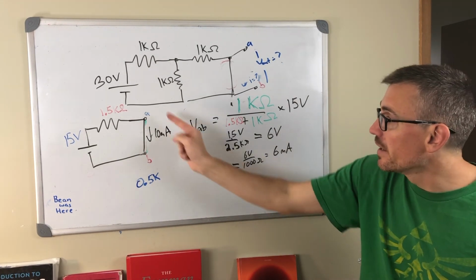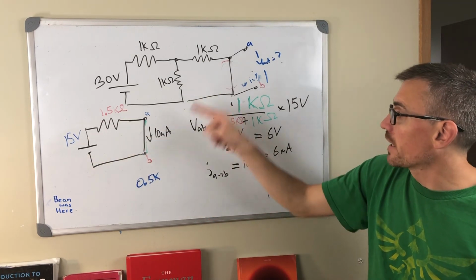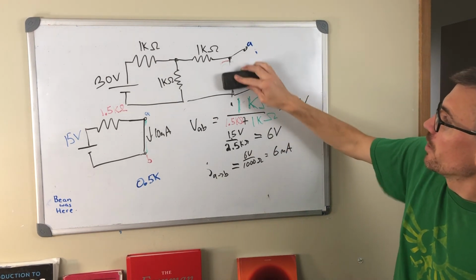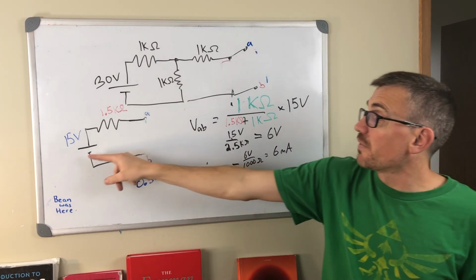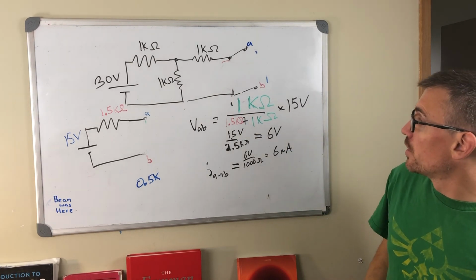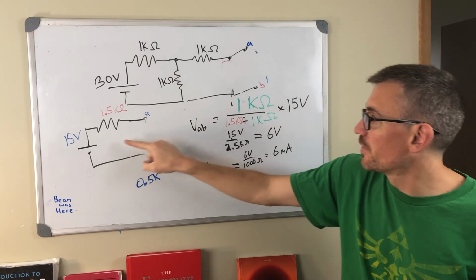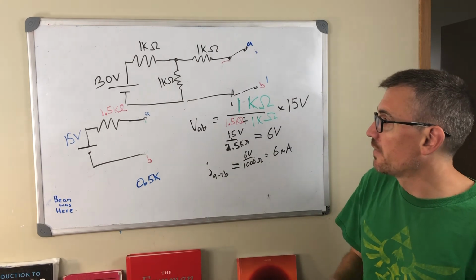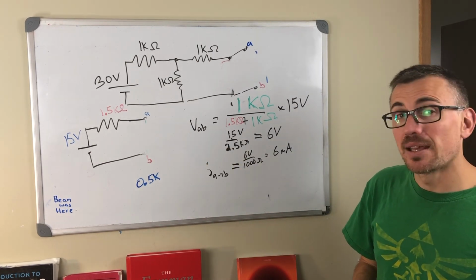Notice that we get that just like that. We get it right away because once we've solved for the Thevenin equivalent circuit, we can plug anything in there. If I forgot to put a resistor at all, I just let that 1K hang there, I'm going to get 15 volts across here. So I'm going to get 6 volts for 1K, 15 volts if there's infinite resistance, or probably about the same if I have like a 10 mega ohm load here. And if I accidentally short it out, I'm going to get a maximum current through here of 10 milliamps.